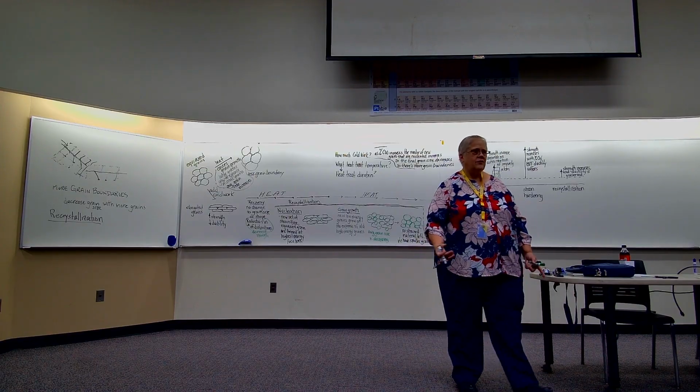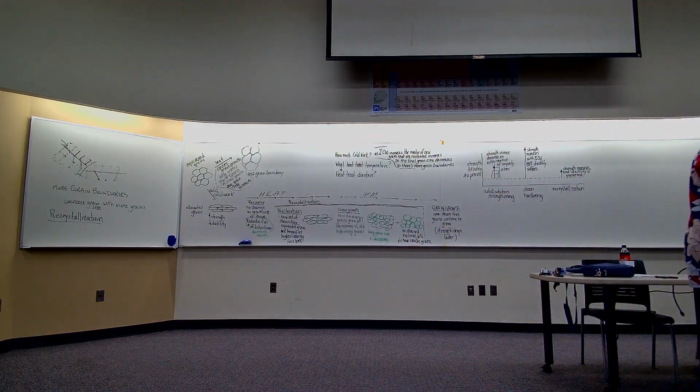So then the last question is, how will I know when that time is? How will I know when recrystallization is actually over? What could I do? Well, that's the experiment. Once you decide on the percent cold work, then you choose a temperature where you can actually manage this, and then you take the piece out at varying times.